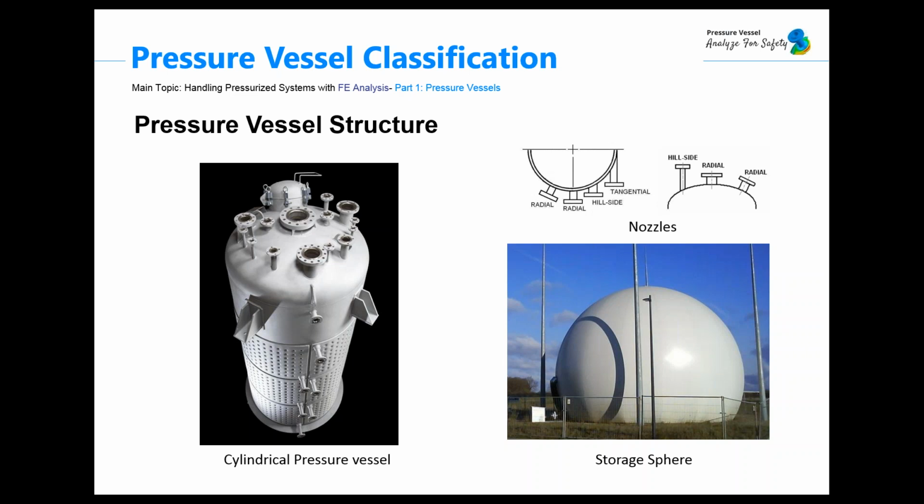But depending on the type and purpose of the pressure vessel, they have some number of openings, especially if we take a look at this pressure vessel on the left. Openings in pressure vessels are necessary to carry on normal operations, and they allow for mounting of equipment, the insertion of instrumentation, and the connection of piping to facilitate the introduction and extraction of content. Openings are generally made in both vessel shells as well as heads, as you see in the picture. Unfortunately, these openings also result in penetrations of the pressure restraining boundary, and as such are seen as discontinuities.